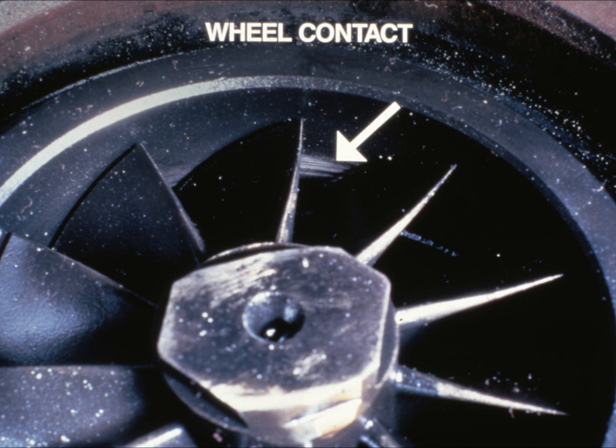Inspect the wheel blades and housing for evidence of wheel rub. Wheel rub can bend the tips of the blades with the housing showing wear or damage. Note any oil or excessive carbon buildup on your list.